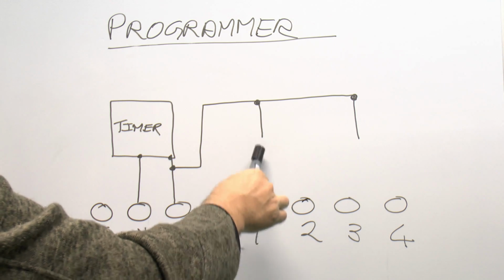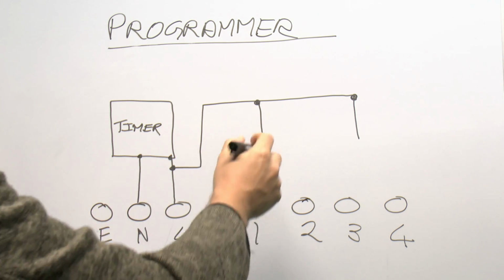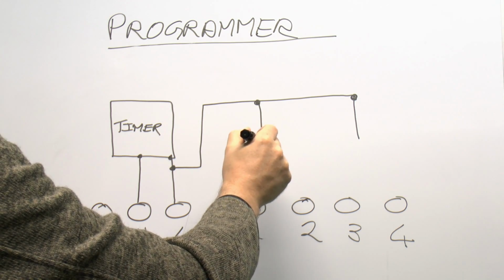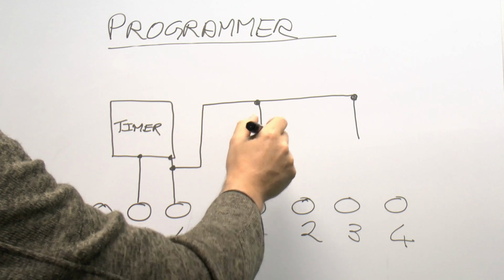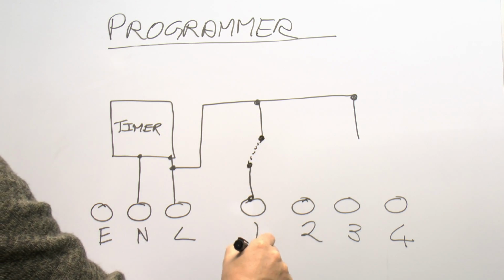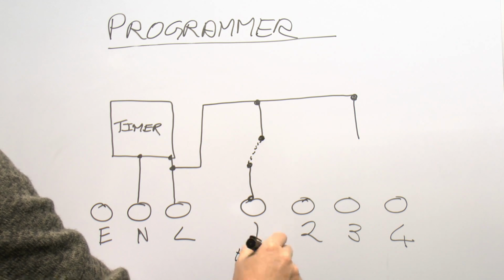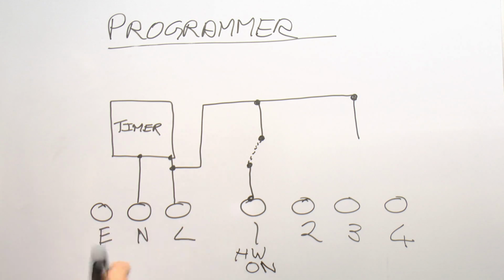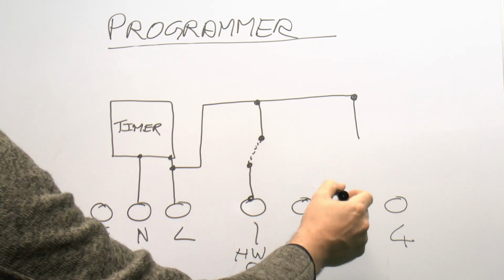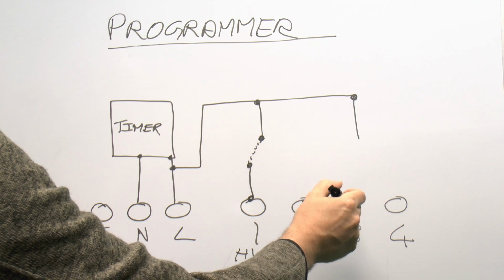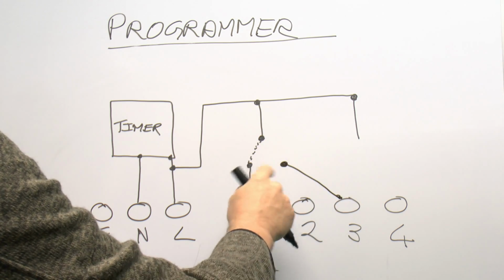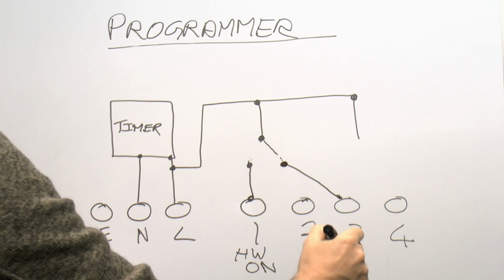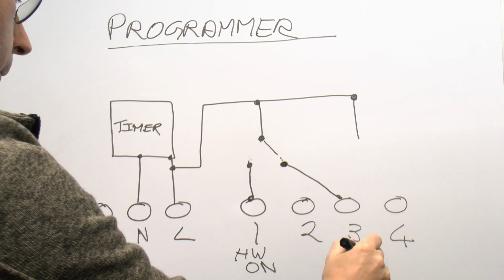And the contact on this side is generally the hot water option, so that will connect from here and over in this position. That's generally the hot water on. So if hot water is required, this terminal is then live, connected via the connection here. And the hot water off is normally the number 3 terminal here, so you've actually got that coming across. And then if hot water is not required, then that contact simply switches over to there, and that's the hot water off.